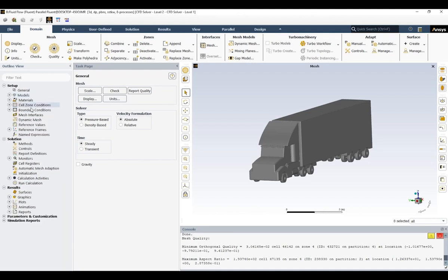And as was mentioned earlier, we will perform the simulation, and in case the y plus value was bigger than 1, we're going to have to go back to the ANSYS meshing in order to make our mesh cells smaller. So for now, I'm going to keep moving further inside the settings that I'm going to apply for the Fluent software.